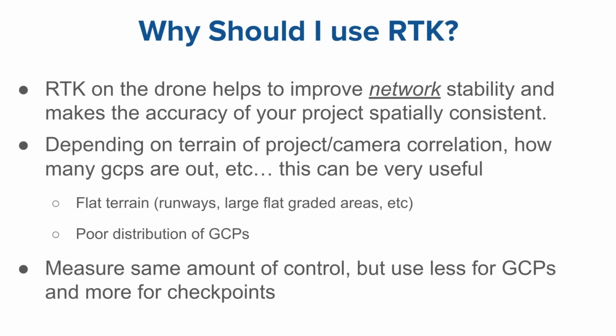Okay, hey, I expect my map, my 3D point cloud, to be within 3 centimeters. I'm going to use this control point as a checkpoint instead, and verify that CPC is doing what it's supposed to, and that my accuracy is within this range. Okay, so that's the beauty. That's my pitch on why RTK and PPK can be very valuable.